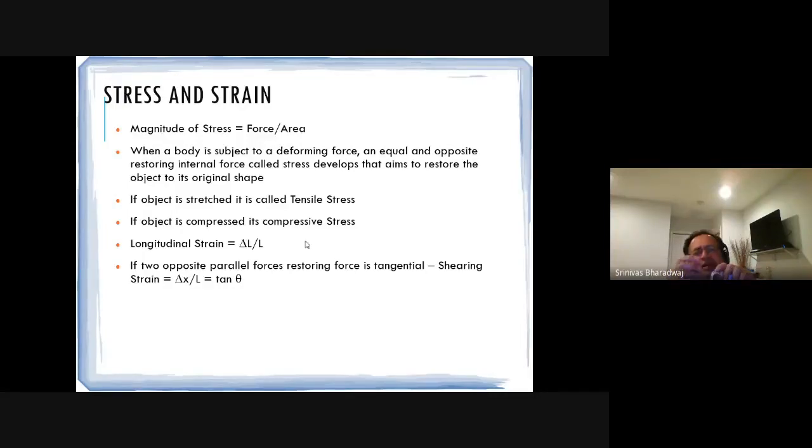Now the area is the cross-sectional area of this. So this might be maybe 1 millimeter by about, this is probably 3/4 of an inch, maybe 2 centimeters. This is my guess. Okay, maybe 2 centimeters by 1 millimeter. So what is the area? 2 times 0.1, right, centimeter to millimeter, 2 times 0.1 would be the area, in cm square.